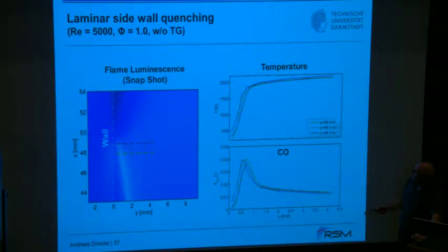And there you see now the temperature profiles. I go through them a bit faster. You see as well the CO profiles. The further downstream you go, the closer the flame actually comes. That is in accordance with this chemiluminescence. Of course, the chemiluminescence at some stage doesn't provide any information anymore, because the reaction rate is already maybe too small and is compensated by that background luminosity.